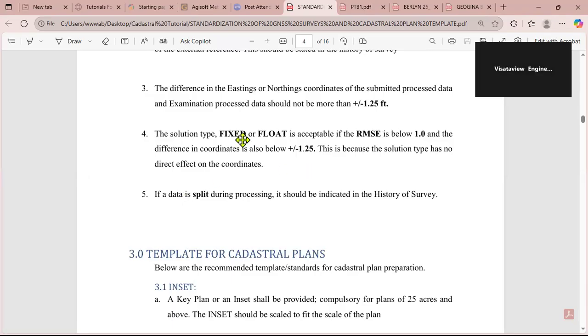You see, you have to set the TBM closer to where you are working. If you are setting your base, you have to set it in a place that someone will not go and remove, like in front of someone's store or a house, and alert the person.